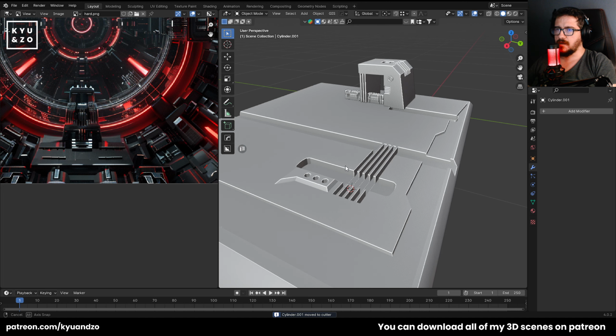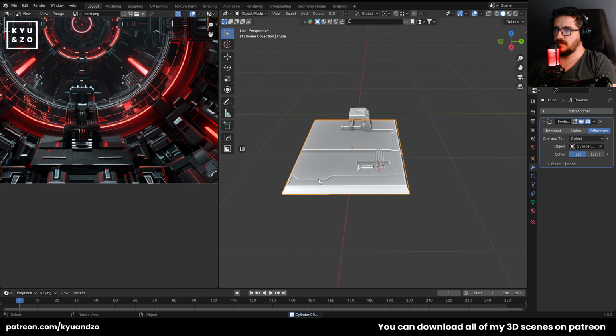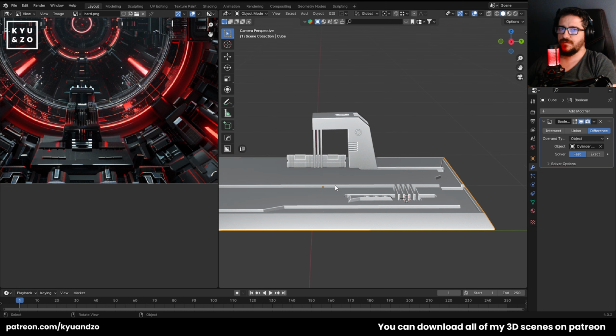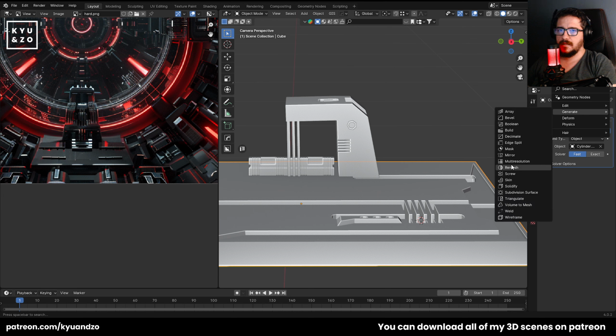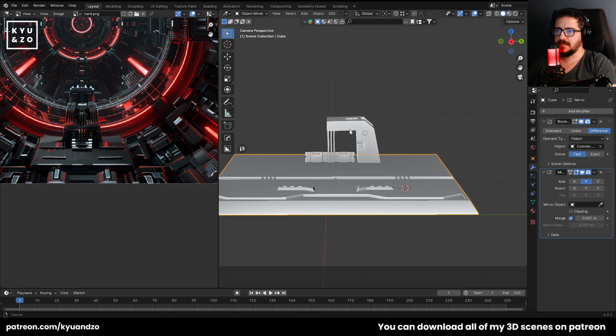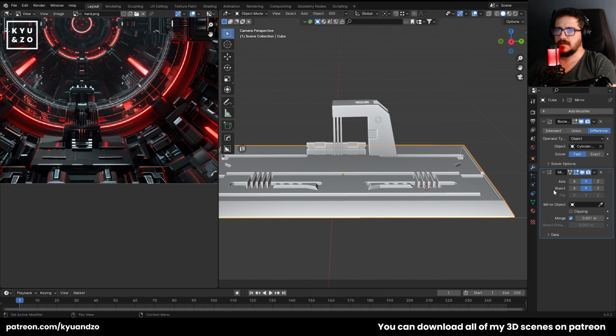Yeah, that's it. And yeah, we have this object here. You can move it to cutter. And look at this. Yeah. All right. We're gonna keep it just like this for now. And I can apply mirror. It's at the y-axis, no, x-axis, bisect, and it's gonna keep everything here just like this, and clipping.